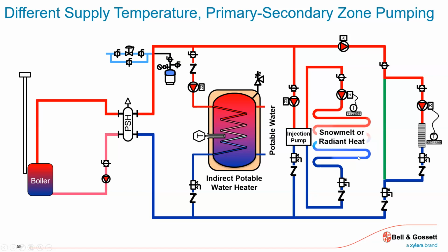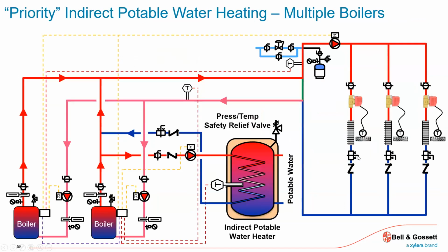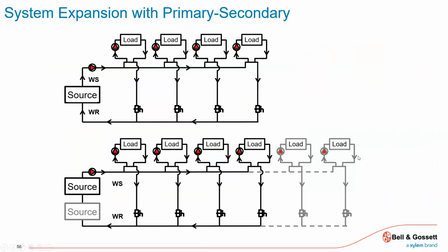Now, how much is a function of the capacity of this pump, and what's the pressure drop through the coil. Each one's going to dictate the flow, but it's out of control at that point. Correct. That's exactly right. Does that make sense? It's pumps in series, and whether it's this guy or it's a set of T's, that's not necessarily the greatest picture. These closely spaced T's, because if that T wasn't there and this pump just went up into that, if that pump was off and this guy's running, he's going through there. We don't want that, but he's absolutely, because he's in series.